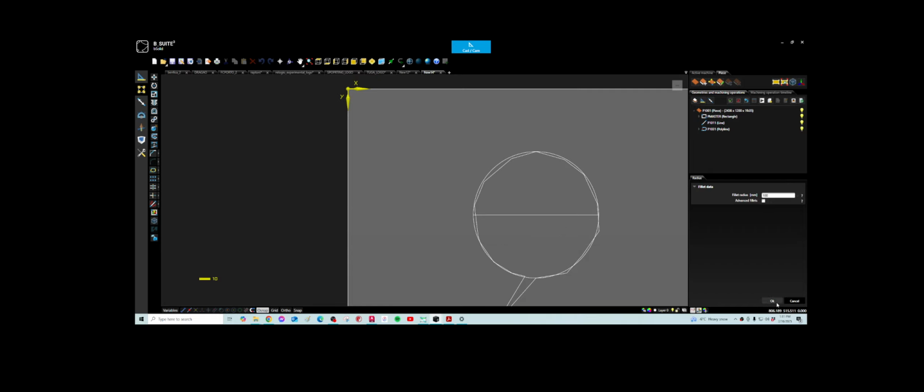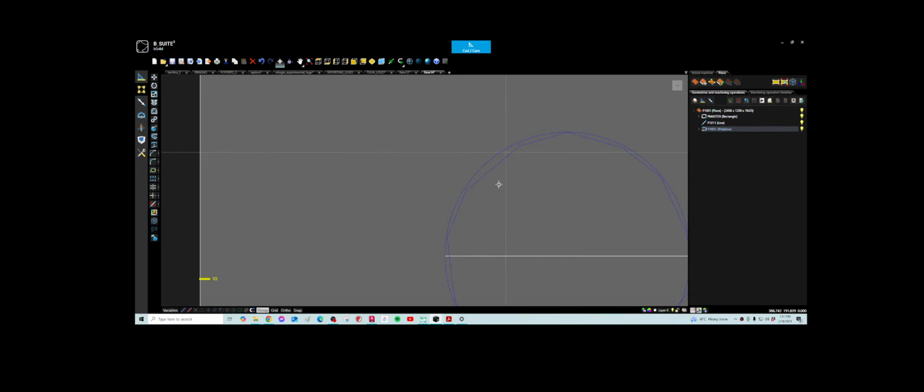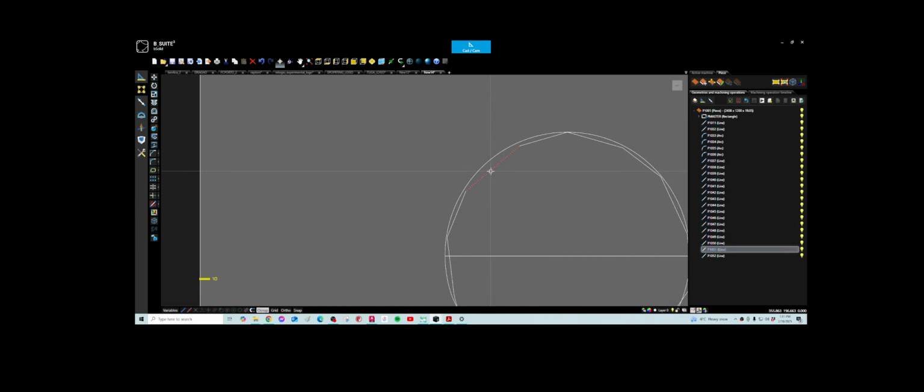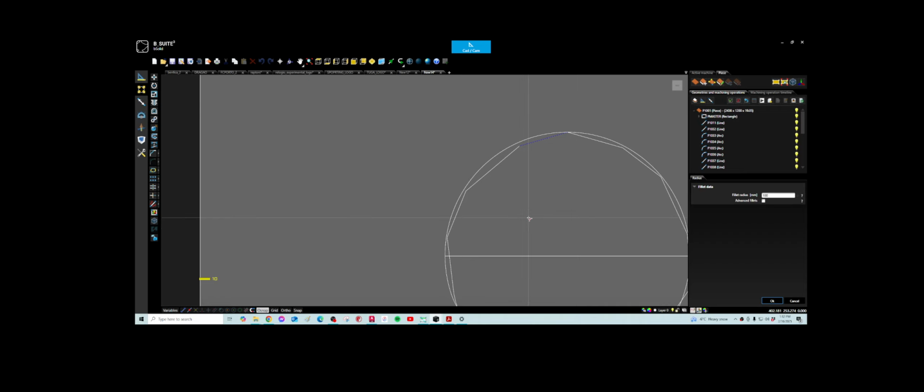Okay, this is a way. Okay, let's say, oh, but I need to move this. I need to move it, and it's all stuck together. I need individual lines. So you go here, press right button, and just explode geometry. This way you have simple lines. See, this is much easier. And now if you have to, you go here, you select your line, you select that one over there. So let's make it 15.